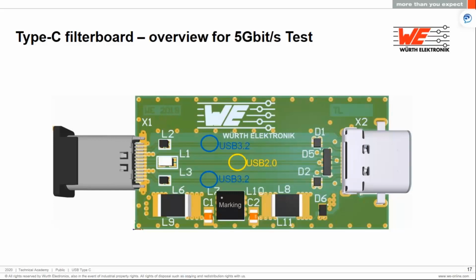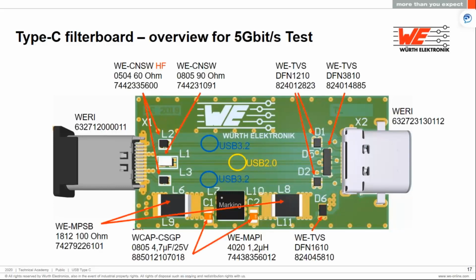Here in this slide, we can see the overview of the dongle and what type of components are used within these dongles. The yellow one we have for low speed lines and control signal here, and the blue one is for high speed such as USB 3.0. And at the bottom, we have a 100-watt power path with 20 volts and 5 amps.